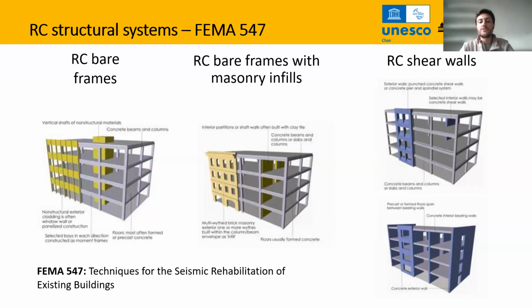We will have a deformation of the internal walls, these infill walls, together with the structural elements, with the columns and beams, and they can therefore get damaged because of the movement of the structure. And the same happens with the facade. Not only internal walls, the facade can also be attached and will then impact the behavior of the structure.